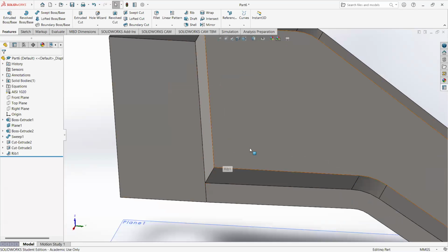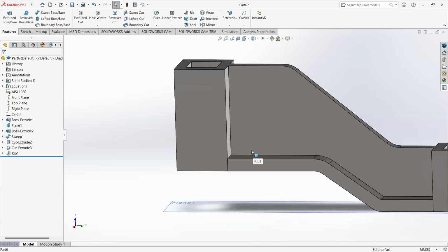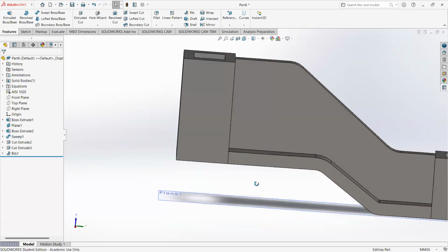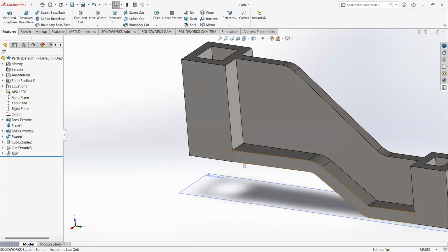We're going to end up with dimensions placing that thing, right? I just drew it in there and left it unconstrained, but it's going to have dimensions. And depending on how we dimension to this and how we dimension to this, modifying a part can pretty easily break other things. So one thing that I recommend if you have to make a modification like that, right, is this.